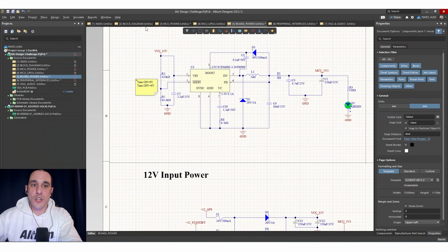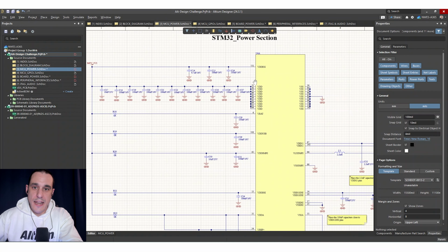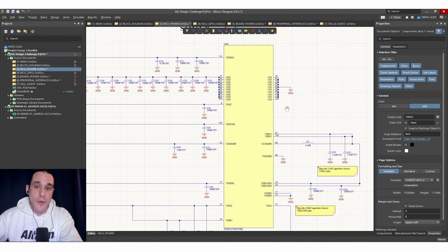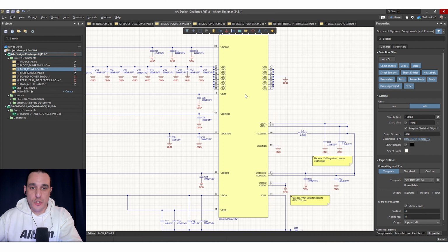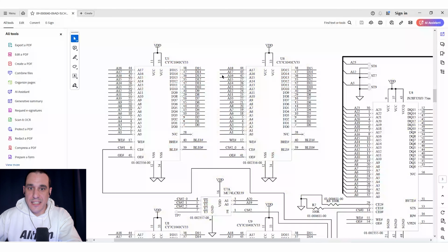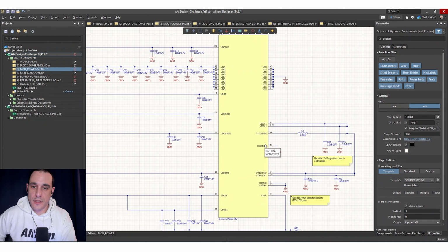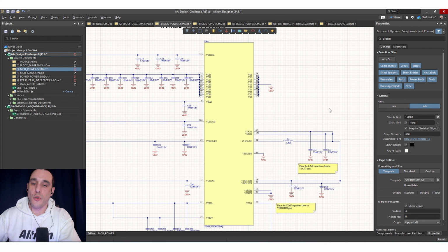Now here, switching over to the MCU with an STM32, this STM32 actually has that much memory built into it, so that's a good choice because it eliminates the need for these two memory chips. So we don't even see these in the updated design. So that's one reason I also think that STM32 is a good choice. Not only is it automotive grade, but it includes all of the memory that was required in order to run the original system built into the chip.